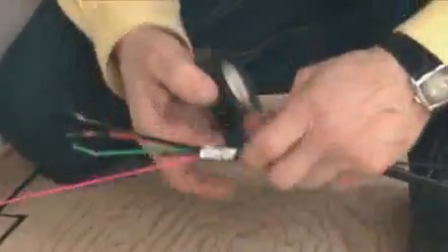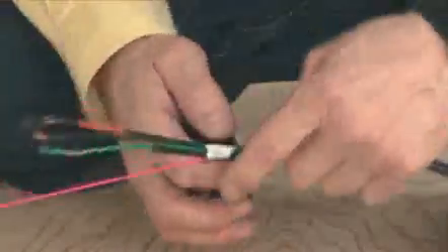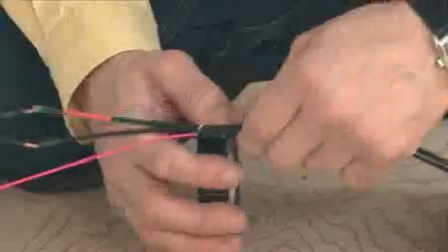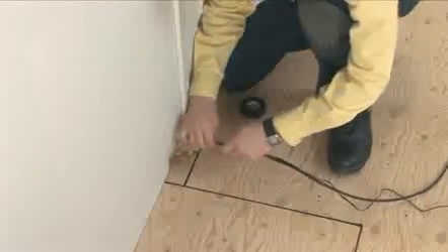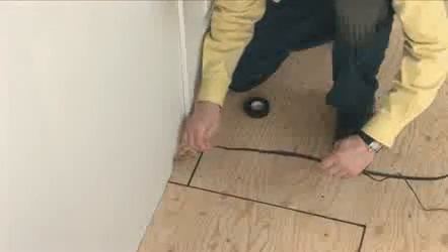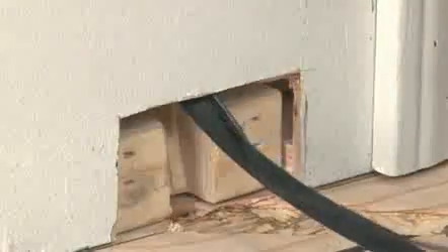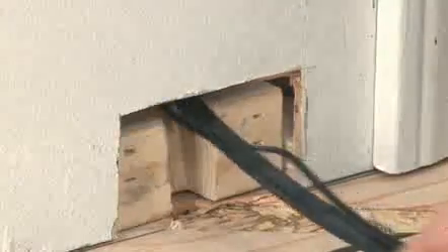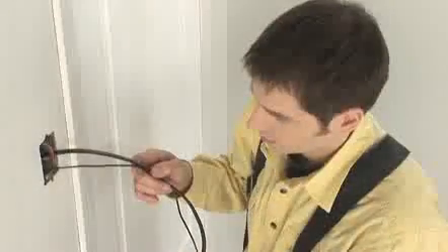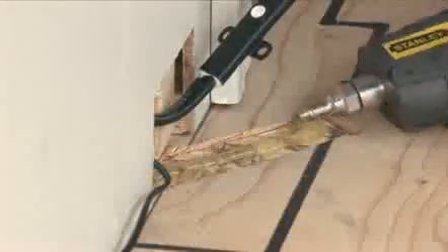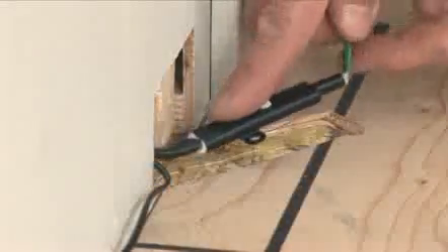Roll up the identification label on the cold lead and secure it with electrical tape. Attach the end of the cold lead and the end of the probe to the cords you previously inserted in the wall. Pull on the cords to raise the cold lead and the probe. Fix the mechanical joint in the groove with hot glue.